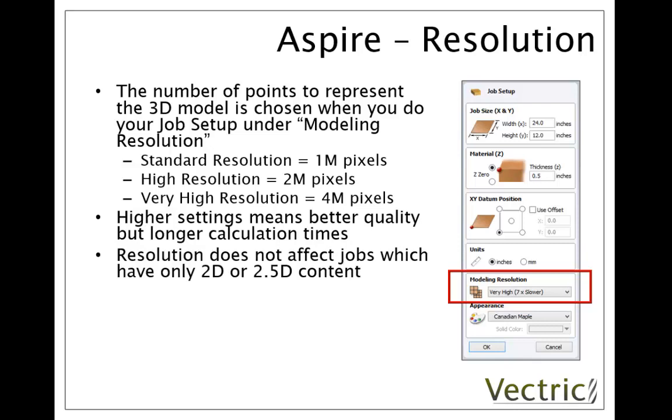It's important to note that if your job only has 2D or 2.5D content, so essentially if you're working with vectors and you're toolpathing those vectors and your part doesn't have any 3D component in it, then the resolution will have no effect on the quality at all. That's going to be all down to the quality of the vectors that you've drawn and the settings you use in the toolpaths.